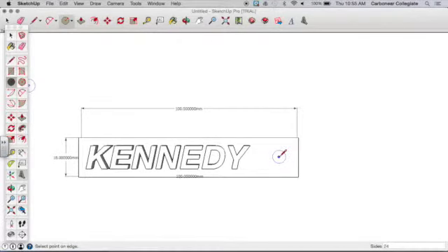And now I can specify the diameter. And we found 3 to be good. Now, once your circle is placed, you can see that it's movable. You can select it, press the M button, and move it closer to the edge if you like.